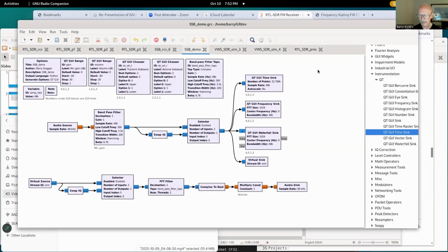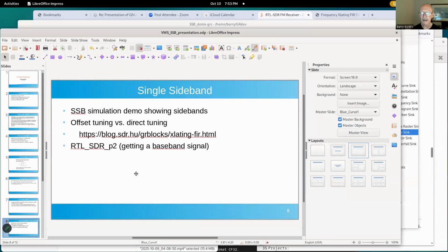Back to the complex data coming out of the analog to digital converters. I and Q together create what's called a complex value. And in that world, frequency isn't just from 0 to infinity in the positive direction. 0 becomes a baseband, basically where you are tuned at the moment, and anything positive is a higher frequency than your 0 reference or baseband, and the negative frequencies are frequencies below your 0 point. I have some illustration for that.